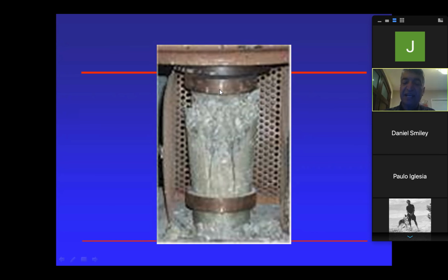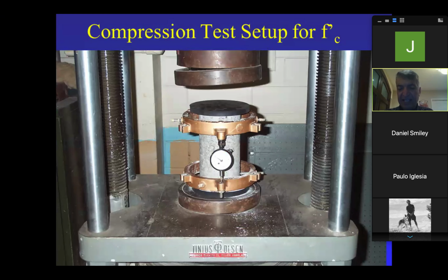That will tell us that the axial load that was applied was concentric, not eccentric. That means no eccentricity in there. It was applied exactly through the centroid. Okay? And then look at something here. What is this piece? This is a piece of rubber. Very strong rubber.